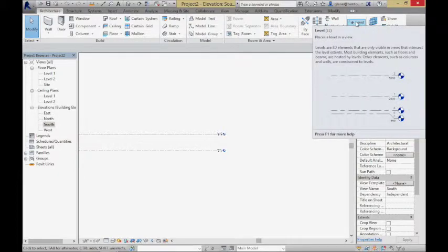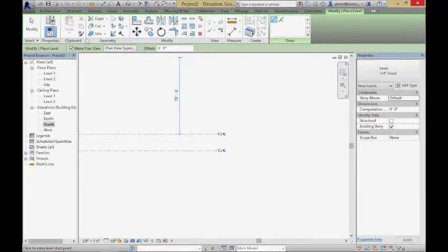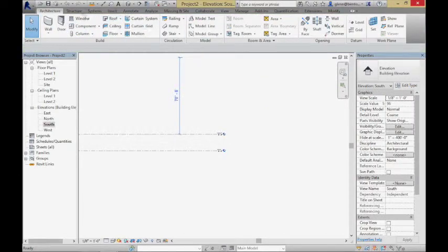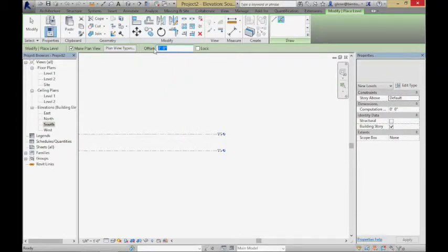We've played around with that a little bit when we talked about levels for the different houses, the multi-level buildings. I can draw levels by just choosing the drawing mode and pulling left to right. That'll actually work. Or I can pick, and I'm going to pick only because it's a very quick way, and use the offsetting tool as a way to create things relatively quickly.